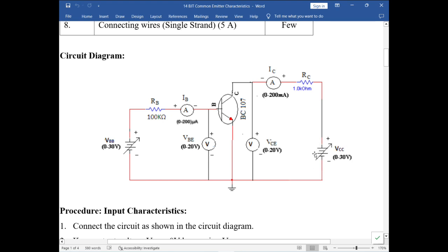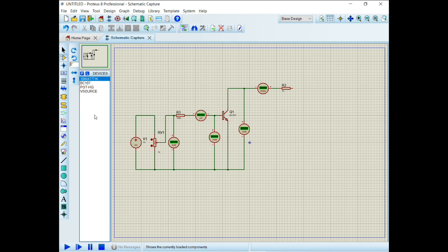And in that case, you are also going to use a potentiometer just as you have done with the input voltage. So go to the components, select the potentiometer, and in this case, you'd want to X mirror it so that it faces the other side. Go to the working area and drop your potentiometer.